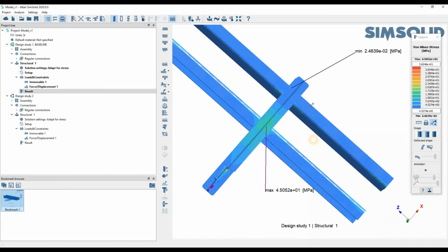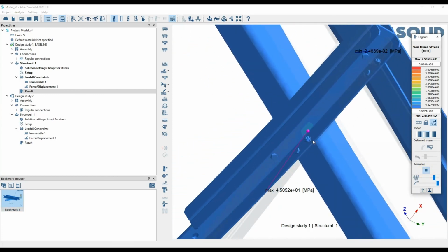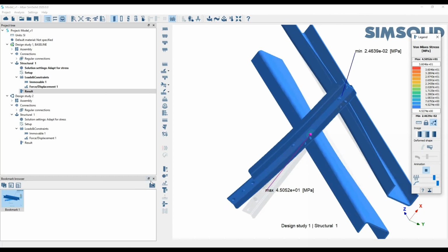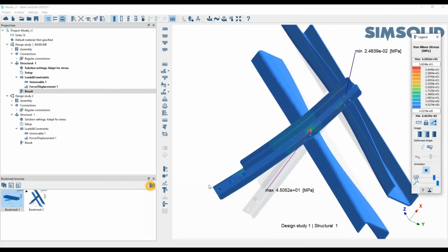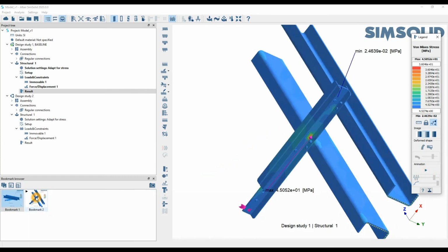If I change the viewpoint of it, so let's say I look at it from here instead, and it's a playing animation. If I was to click on the camera icon here, SimSolid knows that you're playing this animation, so it knows for a fact to save this media file as a video. So if you were to right click on it and save media to file, you'll see that it'll save itself as an MP4. And what this does is enable very quick post-processing.